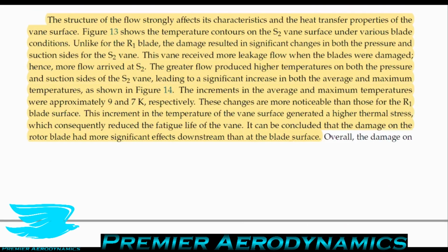So these changes are more noticeable than those for the rotor blades. So the rotor blade is affecting the stator more than the stator is affecting the rotor. The rotor blade affects the stator more than itself in terms of the damage, which comes back to my chemistry anecdote where it's usually the idiot next to you who hurts you, not yourself. So this increment in the temperature of the stator blade surface generated higher thermal stress, which consequently reduced the fatigue life of it. It can be concluded that the damage on the rotor blade had more significant effects downstream than at the blade itself.